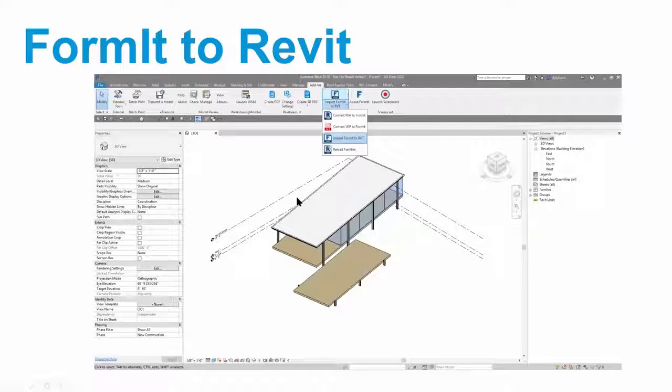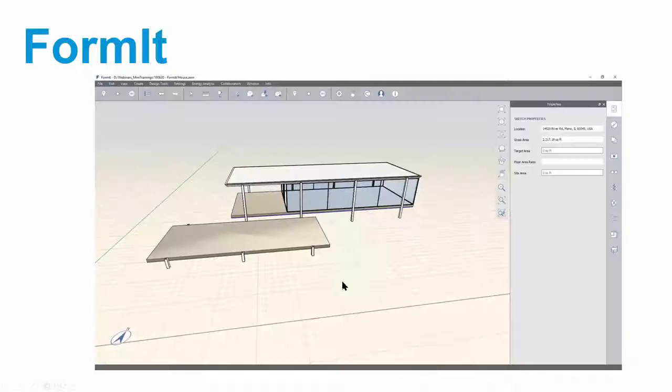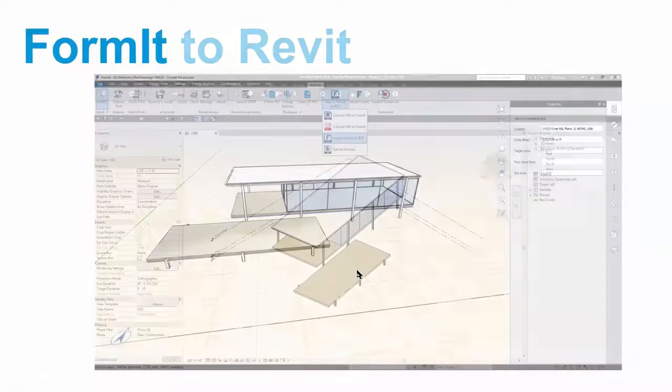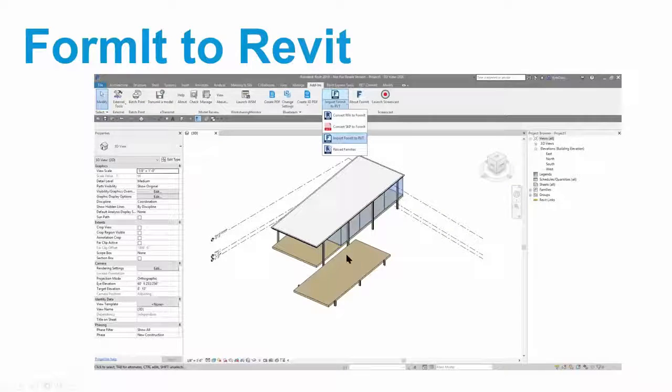But once it's in Revit, since they are masses, you'll be able to use the massing tools to place a floor on the mass. So this is a floor within the Revit model. This will be a mass. So I can do mass floors to create the floor within Revit. The roof, same thing, with roof by face, to be able to place it on the mass, and then also the walls. Be able to use regular walls or curtain walls by face and place them on the face of the mass there. And then the columns will actually be generic model families.